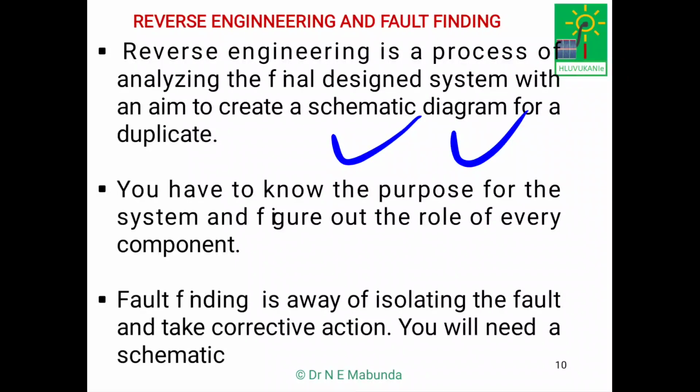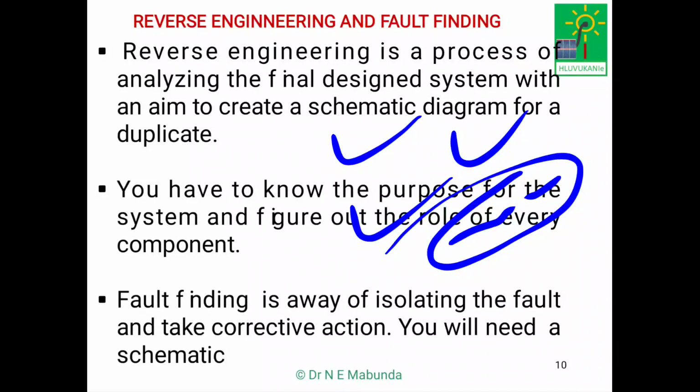Then check your transistor which is used for switching. Finally, maybe check the board if the connections are not broken. So there are many things they will have to check. What they find not working properly, they replace. If it's a switch, they replace it. That process is called fault finding. You don't do guesswork, trial and error. You apply your mind based on what the circuit is doing.